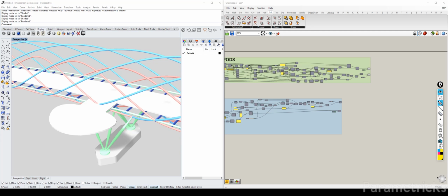So the approach is, let's use the geometry that we have for our deck as some sort of checking tool, to find which of these helices intersects with one of our viewing parts, and where it intersects, we want to extract that helix and cut it, basically cut this part and rejoin them with that part cut, and then rebuild the curve afterwards, and then find a way to make that point join up with that point over there.